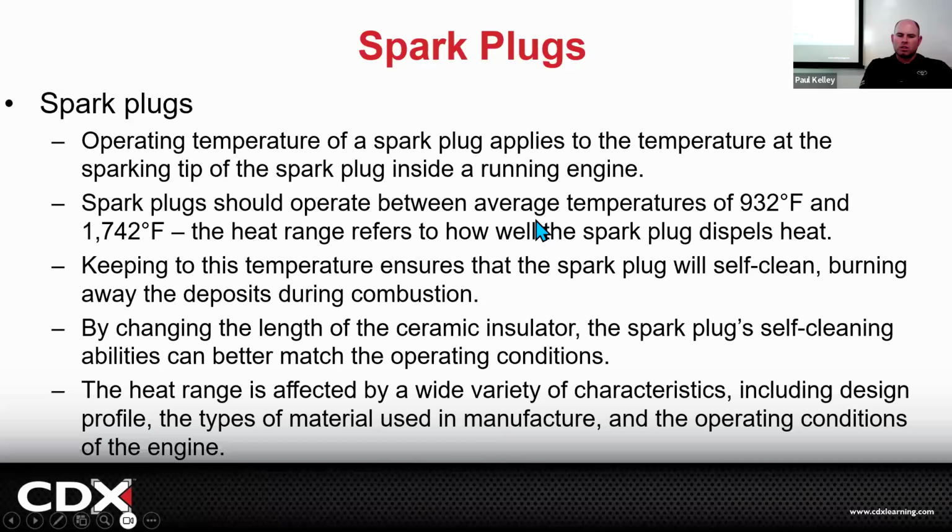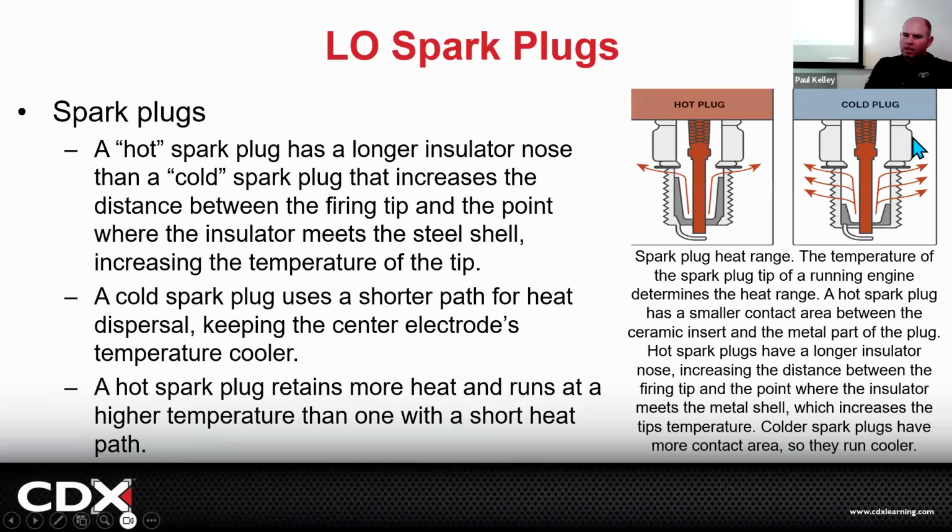Okay. But when you look at the spark plugs, this is going to be a hotter plug. If you notice, this gap right here is fairly small. That's going to keep the heat in and keep it pretty clean. If you run a colder plug, see how there's a bigger gap right here? There's more airflow coming through. That's going to run a little colder.